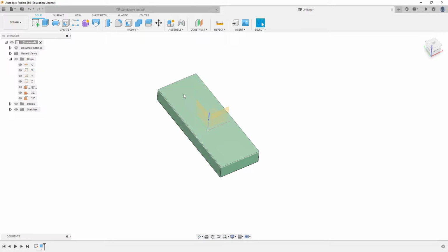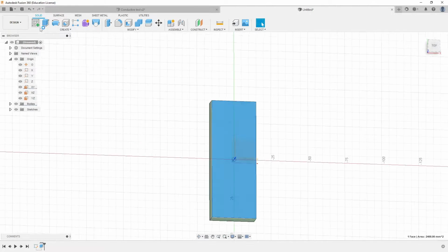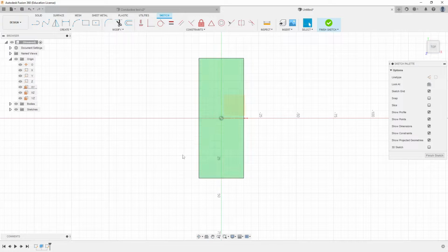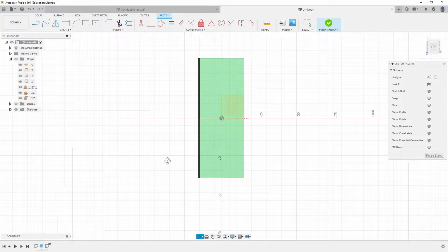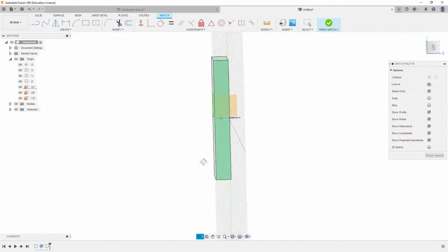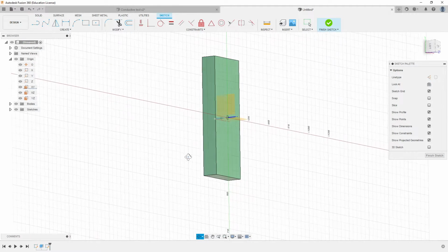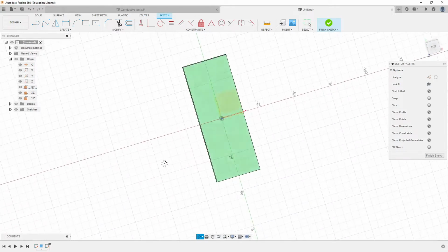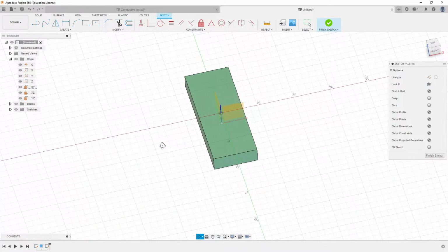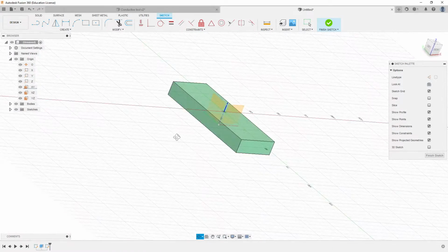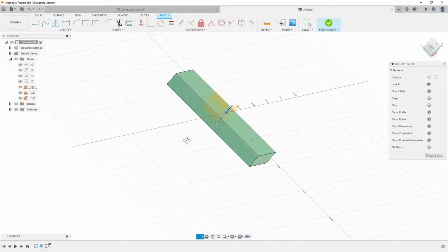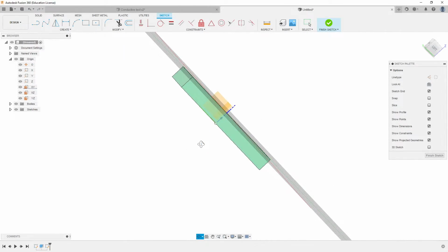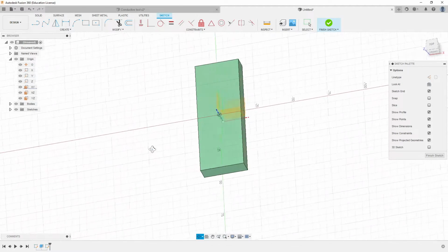I'm going to click on this top face, go here, and I'm looking down at the part. Now, in Sketch, if I tip this off to the side like this, I can see that little mesh, that grid that we call our sketch environment, right? If you hear me say sketcher, that's what CATIA calls it. So we are literally, as you can see, on the top of that face, okay?